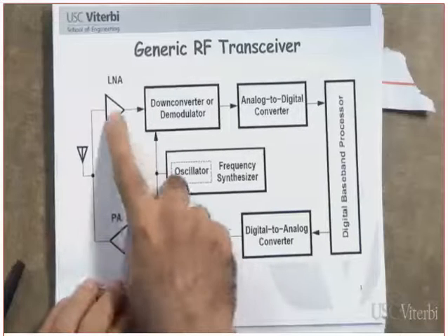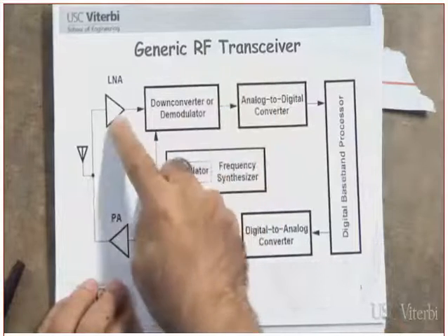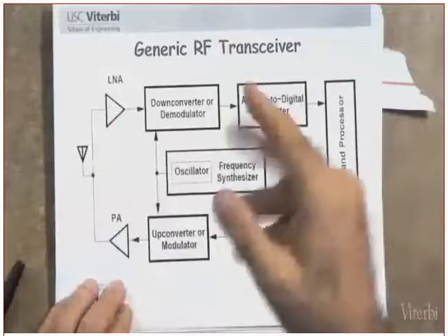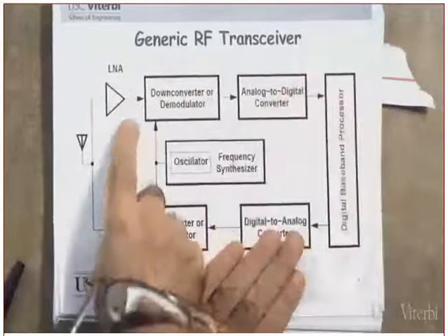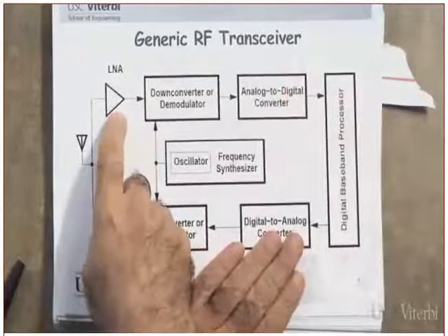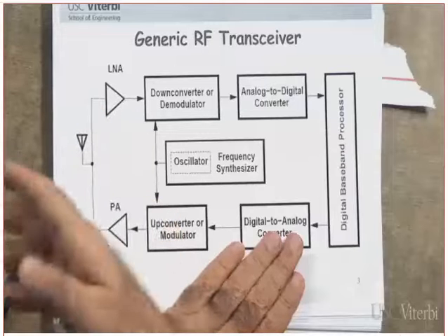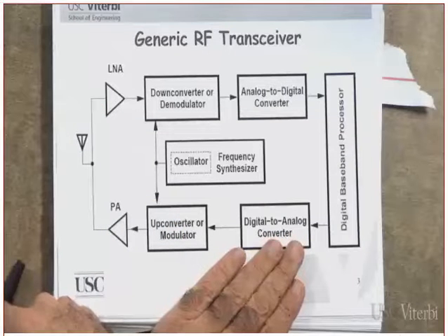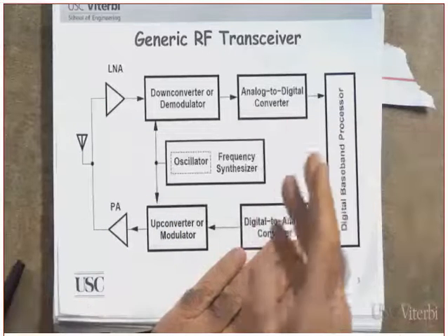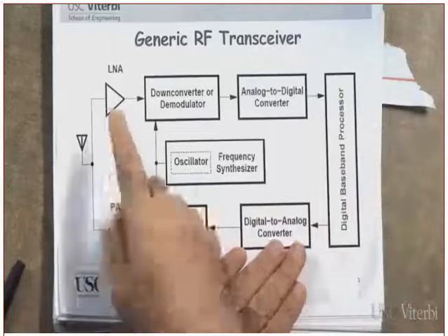We don't want to introduce a lot of noise. By the way, there are no devices that will not add any internal noise. How did they figure this one out? Listen to this. If you design an amplifier, you measure the signal to noise ratio. Did we talk about SNR last time? At least did I bring it? No, I did not. SNR stands for signal to noise ratio. What ratio? Power ratio. Signal power divided by noise power.